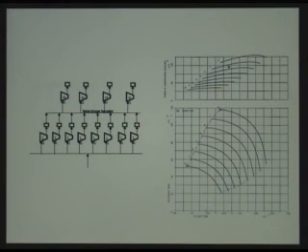You've got 8 machines feeding 4. The interstage pressure can float to whatever pressure happens to be the most beneficial for all the machines at that point in time. As seasons change, the interstage pressure would go up or down depending on how much horsepower is available. When a machine has to be brought down for maintenance, as you drop speed, the interstage pressure will change, and the operators would make adjustments to one of the high-stage machines, and you could pretty well control these 12 compressors.